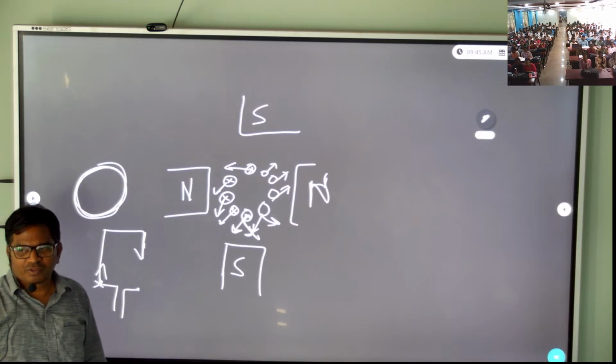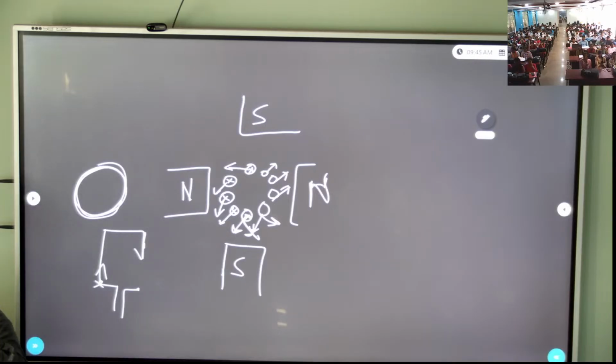So the principle is a current carrying conductor placed in a magnetic field experiences a force. It starts rotating. This conductor is in the magnetic field, so it starts moving like this. Another conductor starts moving. So cumulatively, for all conductors, every conductor keeps moving, and so cumulatively it starts rotating. That is the principle of a DC motor. Construction is equal, there is no difference between them.